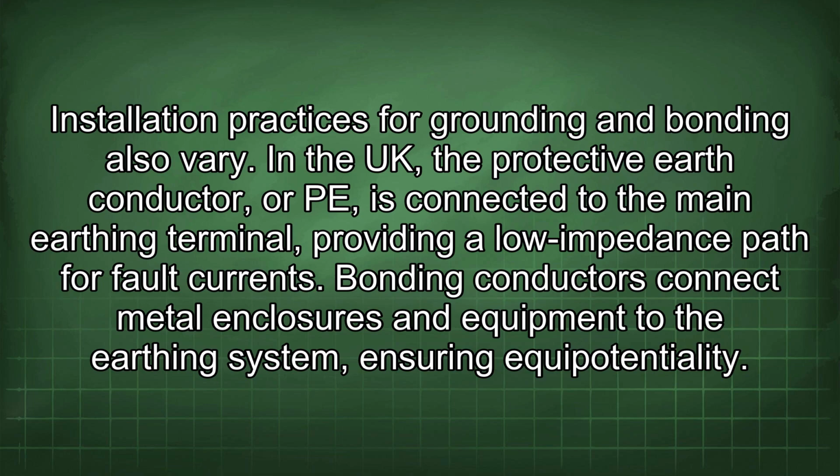In the UK, the protective earth conductor, or PE, is connected to the main earthing terminal, providing a low impedance path for fault currents. Bonding conductors connect metal enclosures and equipment to the earthing system, ensuring equipotentiality.